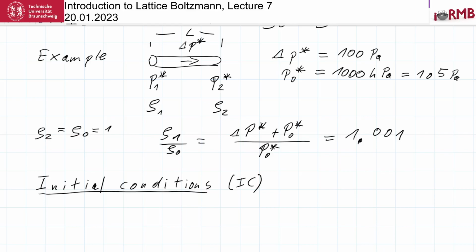So, initial conditions. Initial conditions cannot usually be 0, at least not for the density, because otherwise we generate a vacuum. This is one of the common mistakes that I see appearing the very first time somebody is implementing these things. It has become less common because nowadays nobody is implementing it first of all. They just take something from the internet, I notice, because there are so many implementations already. I'm thinking about a way to avoid this, but anyway.